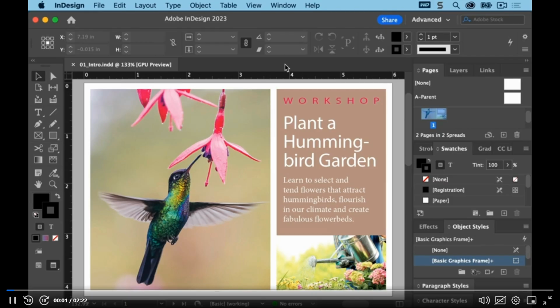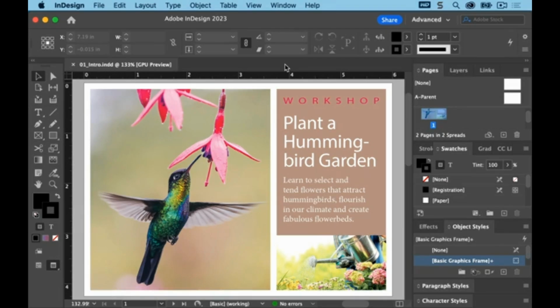In this exercise, you will drag a single panel out of the dock to create a free floating panel. Then you will drag another panel into that panel to create a custom panel group. You will also ungroup the panels, stack them, and minimize them. Locate the Paragraph Styles panel toward the bottom of the panels docked at the right. You will detach this from the dock to create a floating panel.